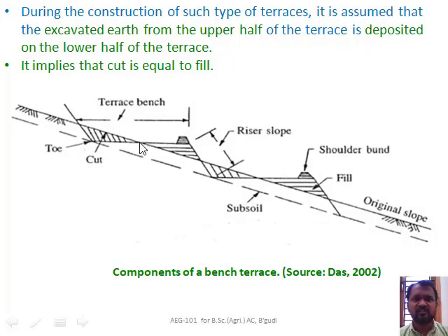During the construction of such terraces, it is assumed that the excavated earth from the upper half of the terrace is deposited on the lower half of the terrace. So here the earth excavated from the upper side will be deposited on the lower side.